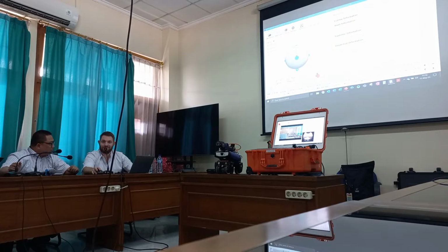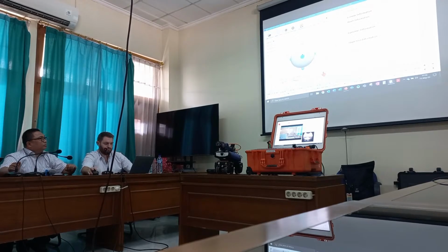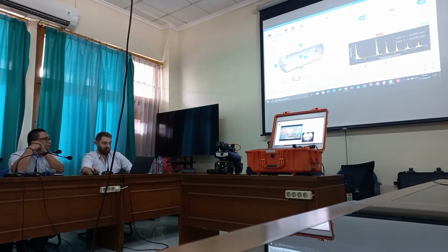So what we've got is we can see our pressure vessel here. We can then cut it open and we can start to see the internals of it and any other aspect that we've got. Down the bottom here we have our inspection timeline. So at every given point in time, all the data and the metadata from this robot is recorded and captured. The steering angles, the light levels, the zoom, where the robot was, where it was looking, where it was facing, all that stuff is recorded.